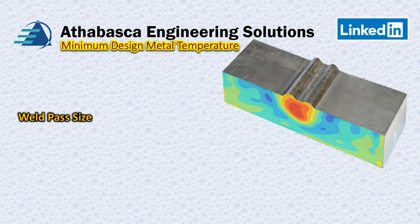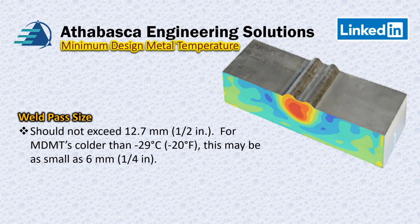An interesting thing about weld pass size: the smaller the weld size, the more preferential it is on the MDMT. Some codes, for example the pressure vessel code, say do not exceed half an inch, 12 millimeters. And if you're colder than that, low temperature, then you may be as small as a quarter of an inch, and that has to do with the heat input, I believe, and how it affects the grain structure of the parent material. And some folks call that temper bead.